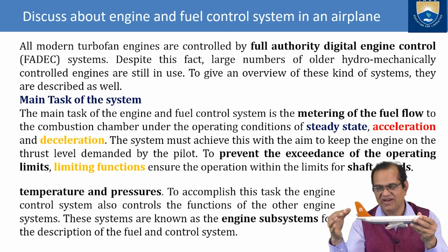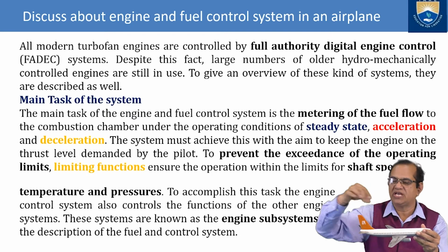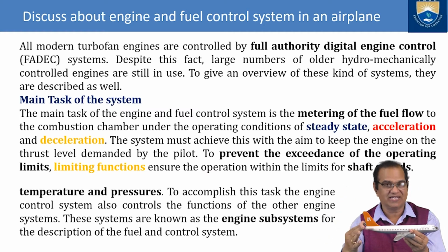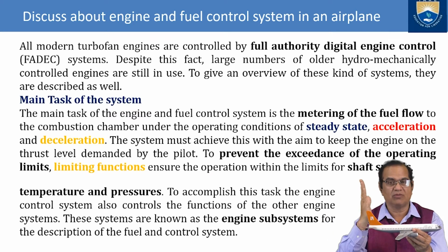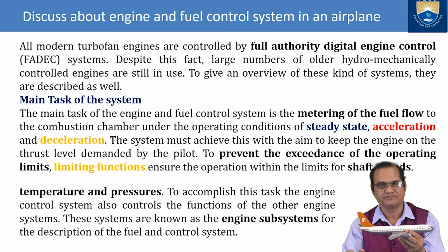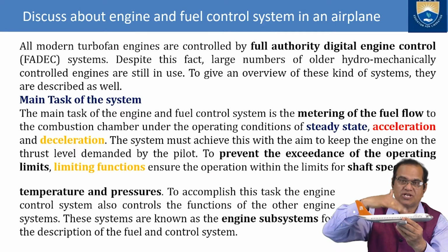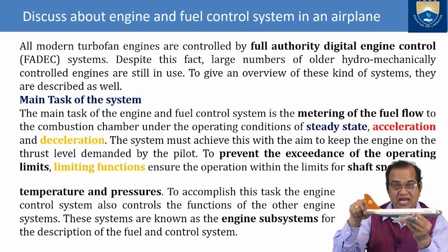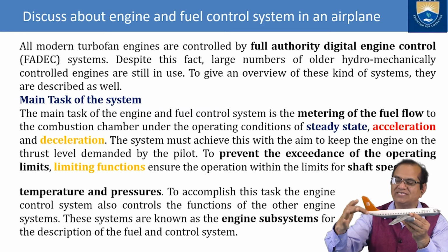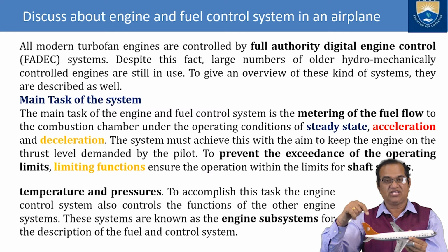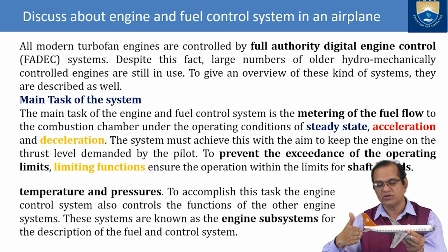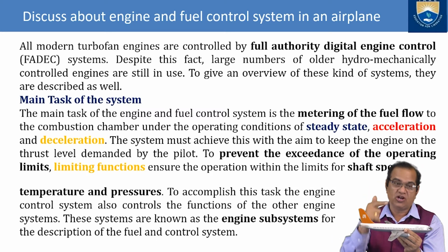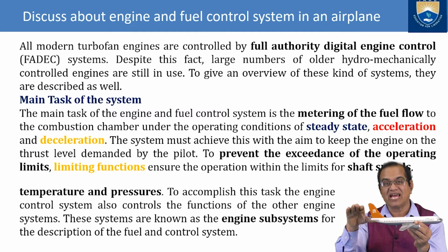They are elevators, ailerons and the rudder. The first control, the elevator, gives the longitudinal motion, that is the pitching motion of the aircraft. This pitching motion is achieved by deflecting the elevator, which is fitted on the horizontal stabilizer. When you move the elevator down, the force will act upward, the tail will go up and the nose will go down. So if you want to make nose down, then this elevator has to go down.